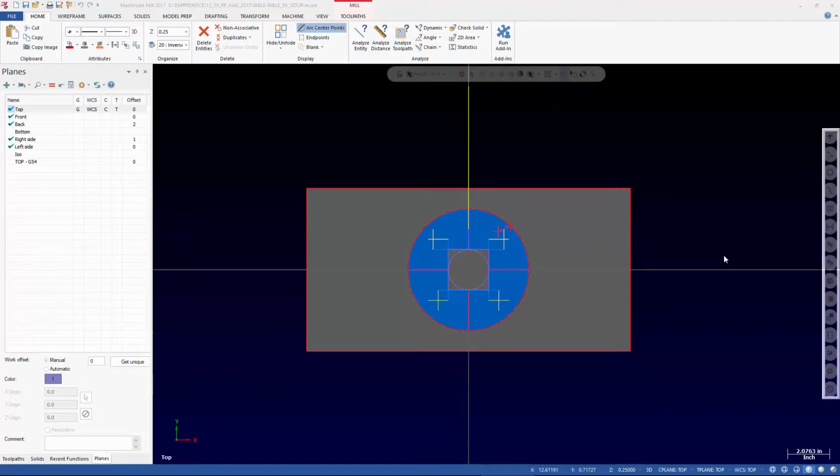So doing some of the more advanced stuff like tool center point control output, we could spend a whole class on that. Same thing kind of with the dynamic work offset. The thing that we are slated to cover is tilted work planes. So I'll show you how to do the configuration and set up the code to calculate the G68.2 output.